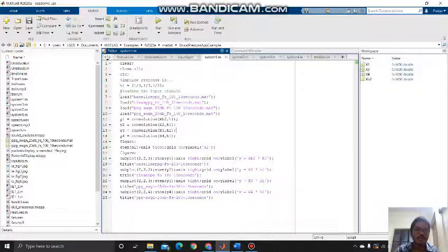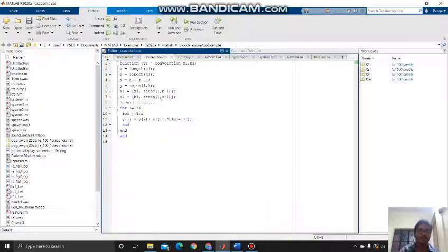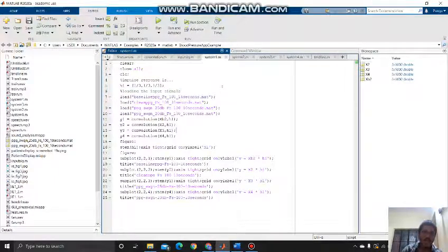After loading all four signals and convolving using the convolution function block, this is the convolution function block. As we know, the length of the output is the length of the input plus the length of the impulse response minus 1. So after writing the convolution function block, we can use it in these four systems.